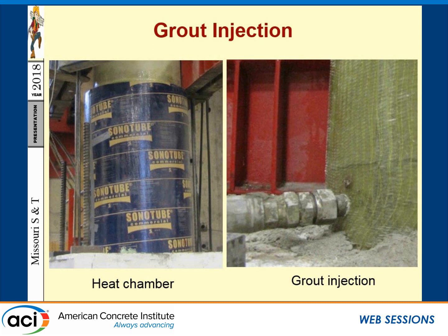So the total thing took only 6 hours. Wrapping 1 hour, 4 hours of curing, injecting epoxy grout for another 1 hour. So it's 6 hours, and we're ready to test the columns.